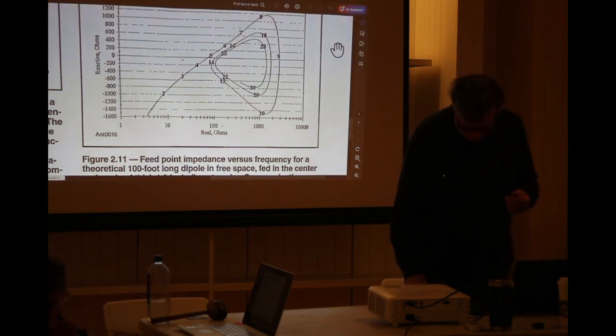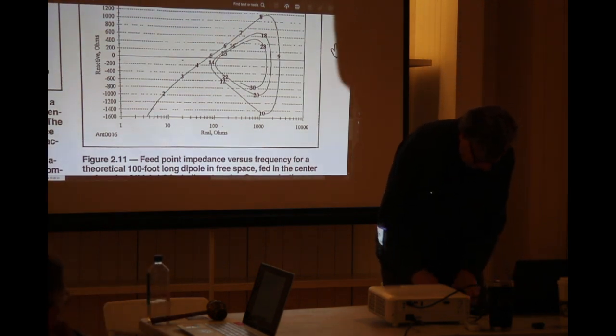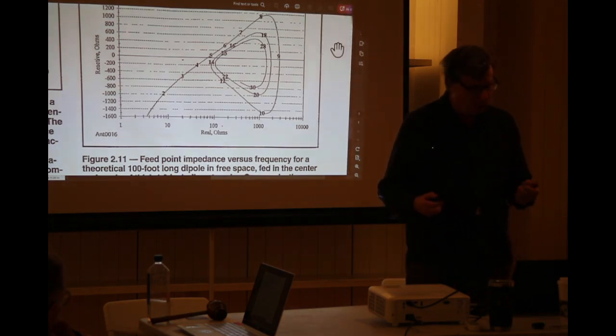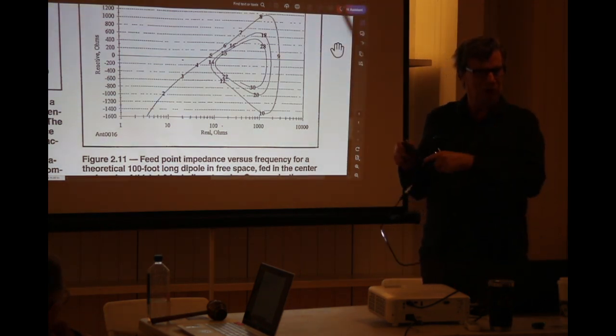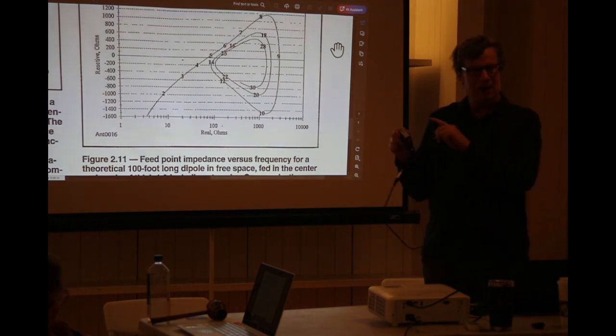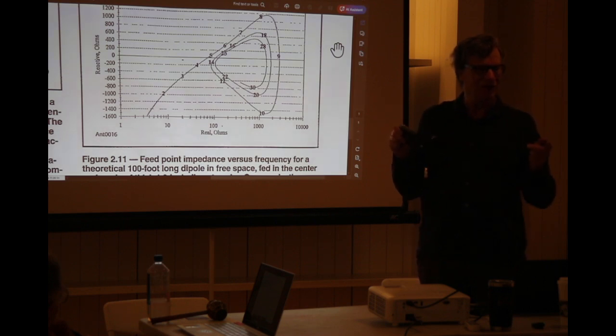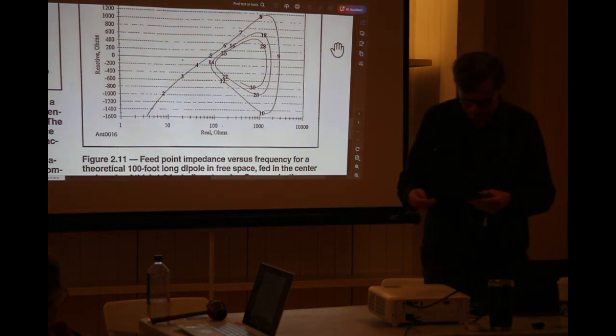But anyway, what we do is you hit calibrate, and by the way, there's a program. It's called NanoVNA Saver, and you can plug your VNA into it. I have a copy of it here. However, when you use that, you can no longer use the front screen, so it takes that over for you. But it gives you a plot of that, and I'll show you how that works at the end here. But for right now, we'll do the calibration procedure.